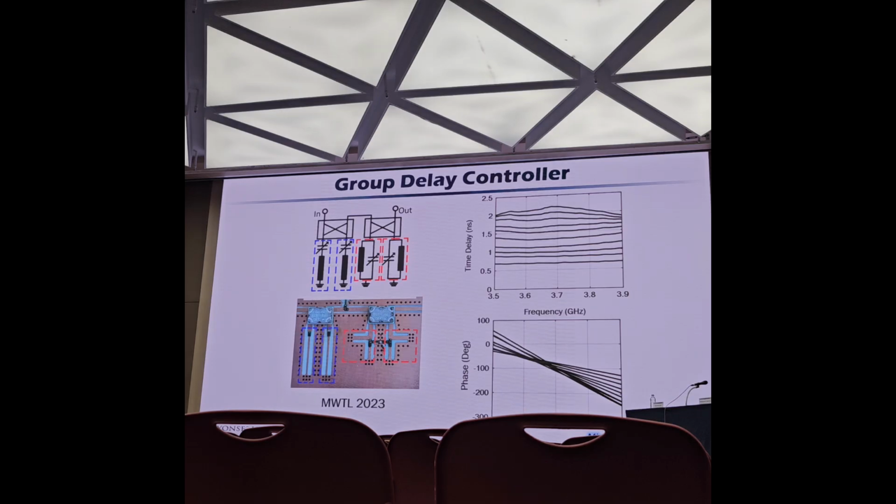Actually, this is at 3.7 GHz. So if we try to use 2 time delays, it's very difficult at this frequency. So it's better to have 1 delay. And as it is narrow band, it's good enough for our system.